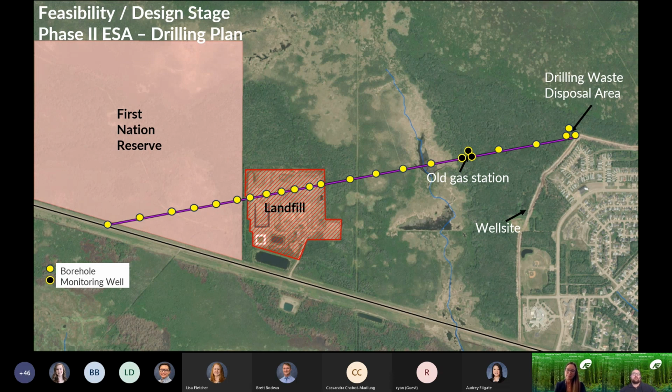It's definitely best practice. Within the City of Edmonton, within their ESA guidebook, for redevelopment of areas, a Phase 1 ESA is only valid for a year, then a Phase 1 ESA update is required. Otherwise, if it's over that 5 years, a brand new full ESA is needed. So we typically run that as our best practice as well. Wonderful, good question.